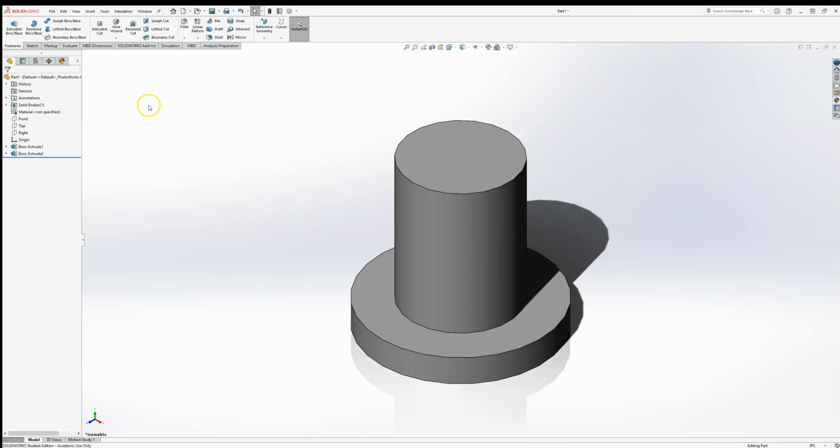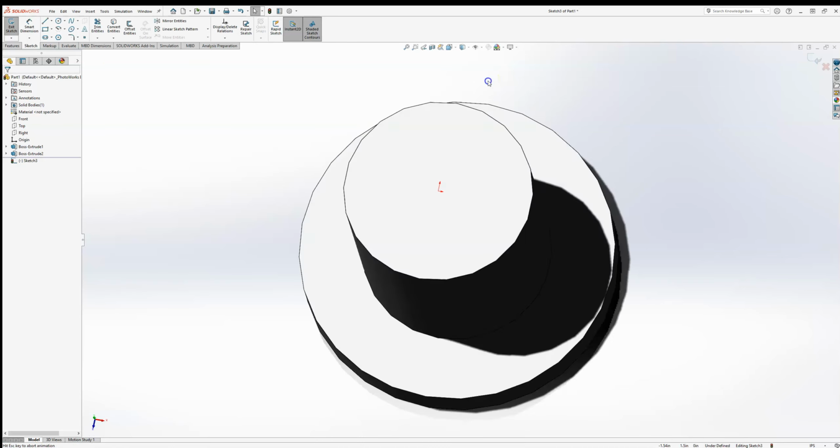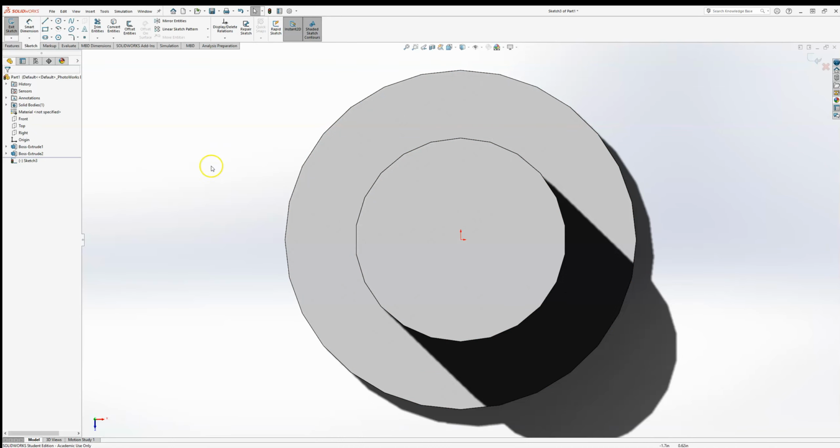And so what we can do is define another sketch. In this case, let's just sketch on the very top face here. So I'll left click on that face, again wait for the quick access icon to show up, and hit create a new sketch. Now you can see I'm in sketch 3, it'll also say editing sketch 3 here. And again, just like last time, I'll use this normal to icon in order to get normal to it.